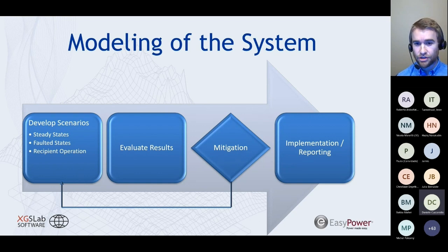So that could be an insulating joint failing, creating a much greater difference in the exposure length of one rail to another. And because there's a shared corridor concern, you could have overall greater induced voltages and greater rail-to-rail voltages. So at this time, I'm going to pull off of the PowerPoint and switch into our modeling software.